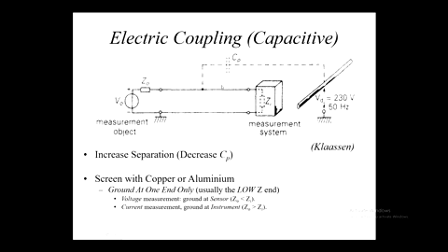So if we connect the shield to ground at this end, it's got a pathway that's not as good at passing that signal directly to ground as it will be at the input. But if it's a current at this end, then the opposite applies, and yes, it's good to ground at the measurement end. Okay.